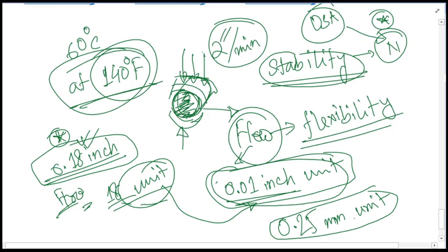So again I am saying the flow value is the total movement or displacement occurring in that particular specimen. First of all, when no load was given, the deformation will be treated as 0, and after load has been applied and the maximum stability value before failure has been obtained, the deformation will be taken again. If the initial value is recorded as 0, then the difference between these two deformations will be taken as the flow value finally. Okay.